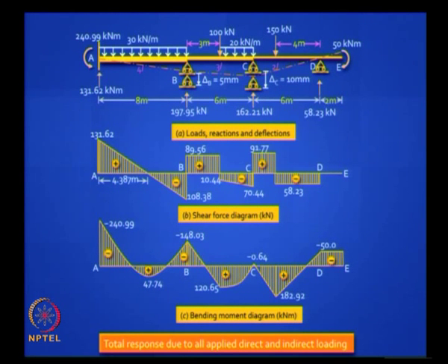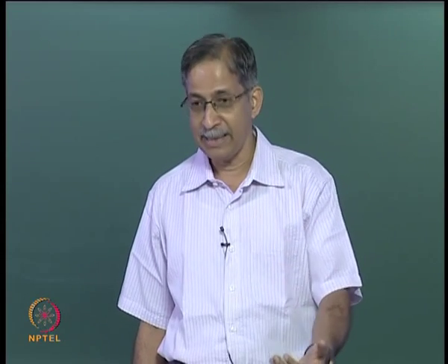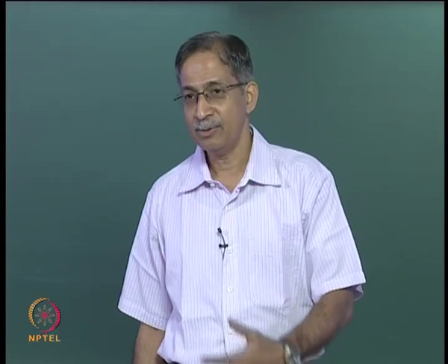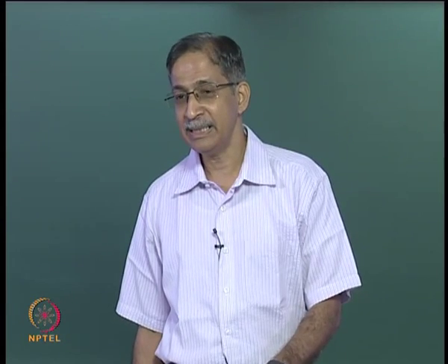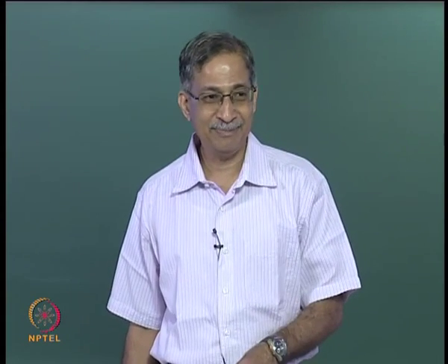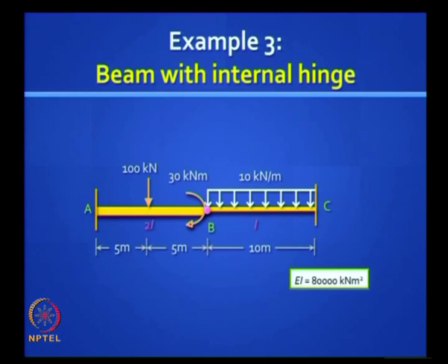Is this clear? It is a powerful shortcut method. Instead of solving for 5 unknown displacements, we solved for only 2. Our interest was to get the final solution, to design this beam, so we need to know the bending moment diagram and shear force diagram, and we have got it. We will do the same problem tomorrow using the flexibility method, and you can decide which is the easiest to do. Okay, we have not done this in moment distribution or slope deflection method.